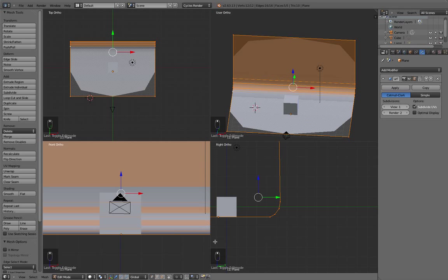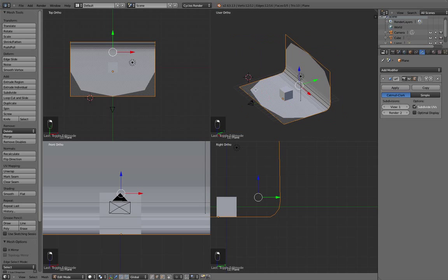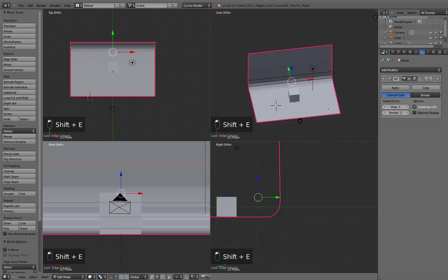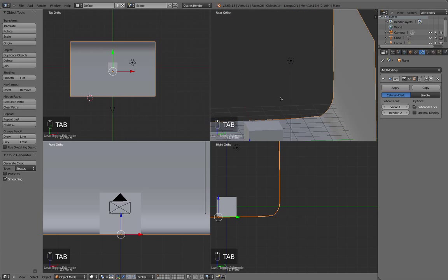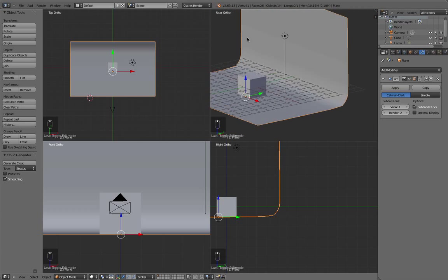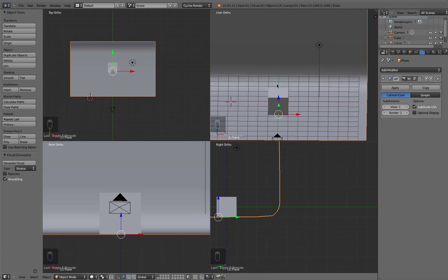select the edge loops there, and I'm just going to go into edge selection mode and press C on my keyboard to do a brush selection, and then I'm just going to middle mouse button to select everything but the perimeter edges there. Then I'm just going to go Shift E and drag out to mark those sharp, which gives us a fairly smooth backdrop.